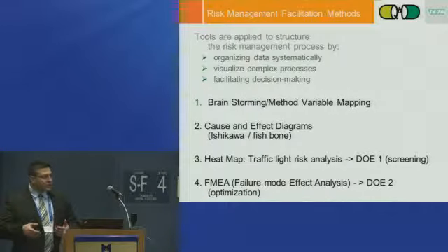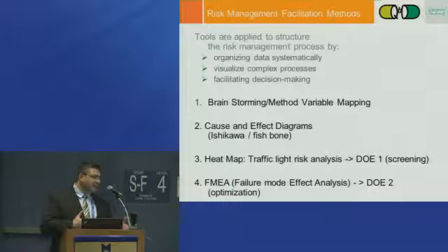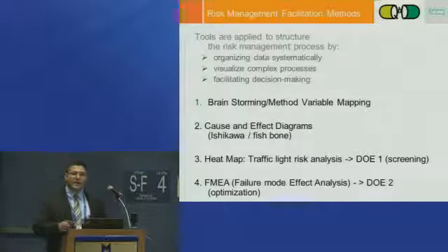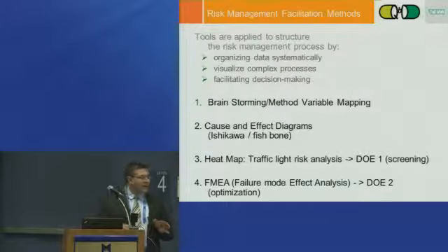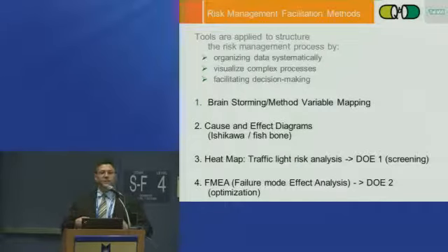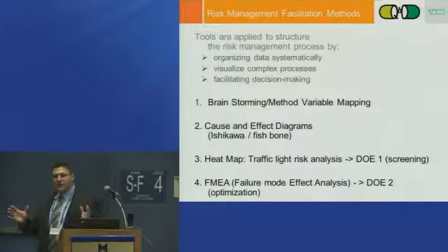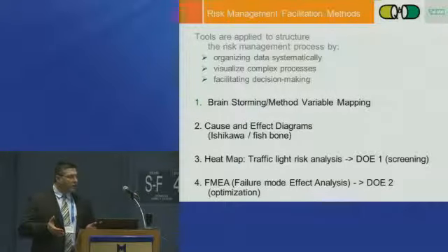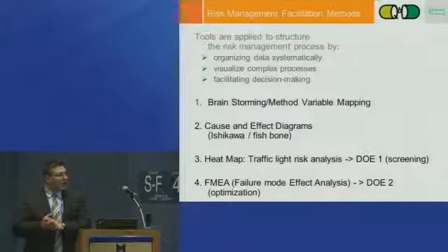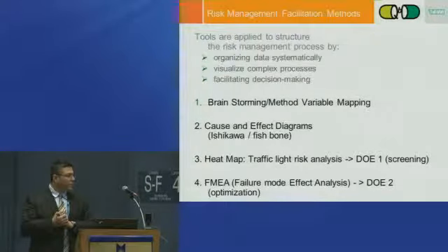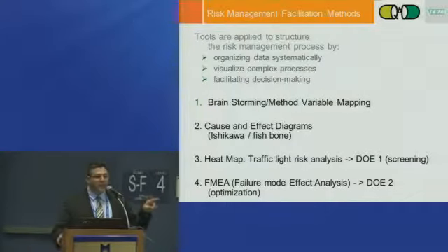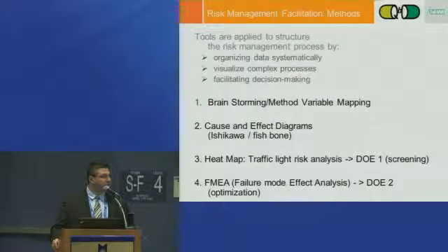Later on, after the formulation process gets locked, or the API process gets locked if you're on the API side of things, you would then do a more formal type of risk analysis, which is a failure mode effect analysis. And then after that, you would do an optimization DOE. At this time, the number of variables have probably been narrowed down to a few of them, 2, 3, or 4. Here, you could do a full factorial with some replicate analysis and then possibly a partial factorial if you still had a high number of variables. And then based on the outcome of that DOE, you would go ahead and update your FMEA and then have the appropriate control strategy. I'll emphasize these points with examples in the rest of the talk.